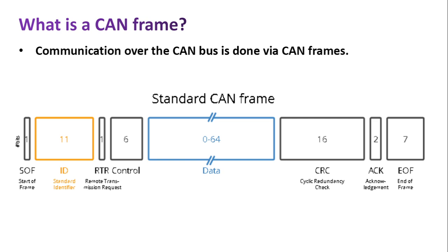So these types of functions are performed using this frame. Okay, this is the CAN frame. Just like when one signal is received here, it is identified as being for the XYZ feature, then it is decoded and the action is taken, and here you can see the acknowledgement and end of the frame, right?